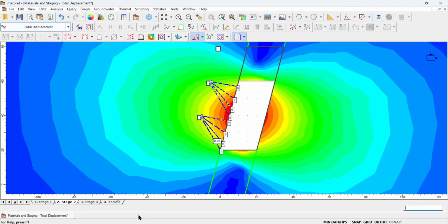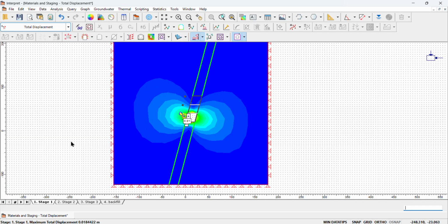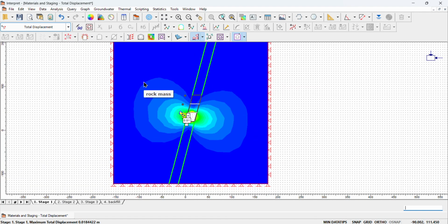Then go for the initial stage. This is stage 1. I think we have done the analysis of principal stresses and stress trajectories, and one more tool, the window tool, which lets us analyze all stages at a time, including strength factors, total displacement, and rock bolts. This is the information regarding this entire experiment. I think it is fruitful for you. Thank you.